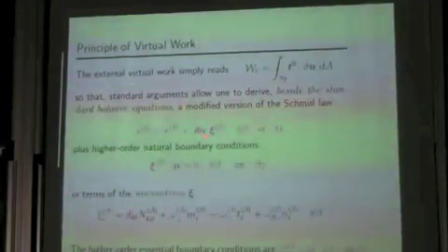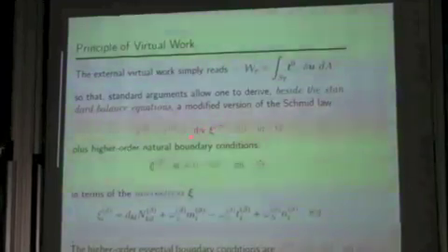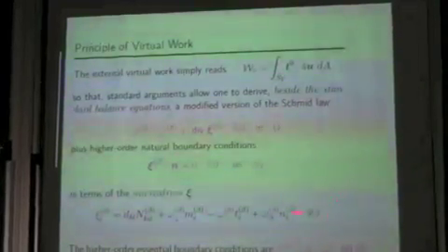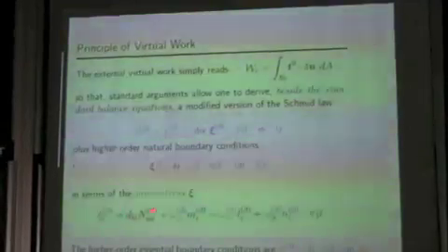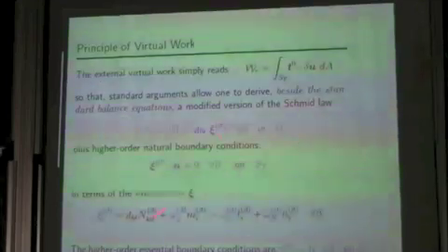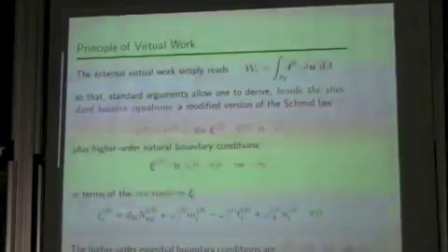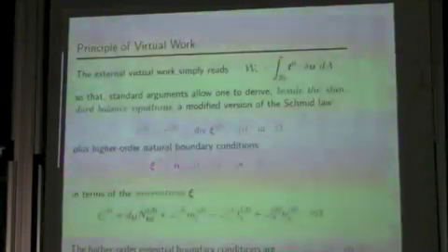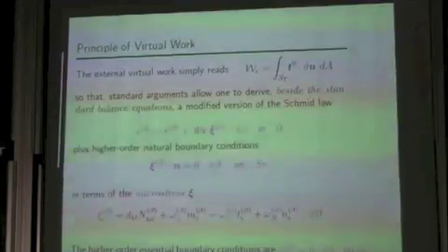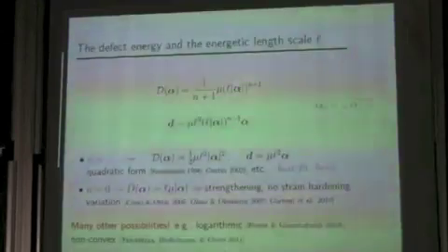In this case, we have this extra term, and this micro stress accounts for all the contributions, energetic and dissipative higher order stress, in this equation. And of course, we don't use in this benchmark these natural boundary conditions. As I said, we just say that each slip component has to be 0 on the boundary.